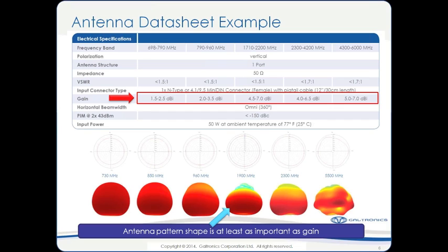So you can imagine, without multipath, I'm not able to achieve my 54 megabits per second or whatever 100 megabits per second that are available. That's because the two messages are correlated, and when they're correlated, I'm not actually able to separate the information well. Now, when I have decorrelation between the signals, I'm more able to separate those signals, and the way that you get decorrelation is through the introduction of multipath.